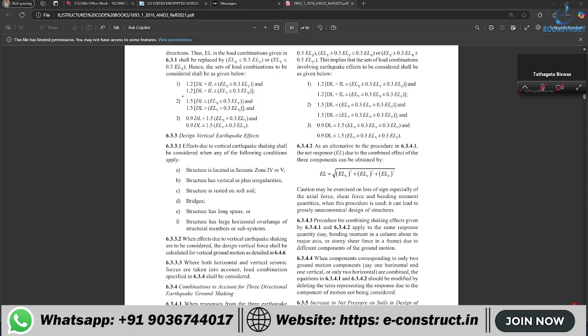It is a very distinct mode. If it is, then we will be opting for SRSS. Why? Because it calculates each mode's behavior separately and doesn't create any kind of inter-mode discussion.